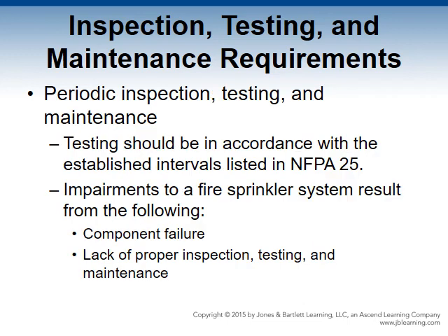Periodic inspection, testing, and maintenance. Testing should be in accordance with the established intervals listed in your NFPA 25 standard. Testing and maintenance of water-based fire protection systems. A simple visual inspection of a system can reveal leaks, corrosions, and damage to critical system components. Water flow tests can determine if the system is still able to provide the required water capacity and pressure, or determine if there is a closed system control valve.